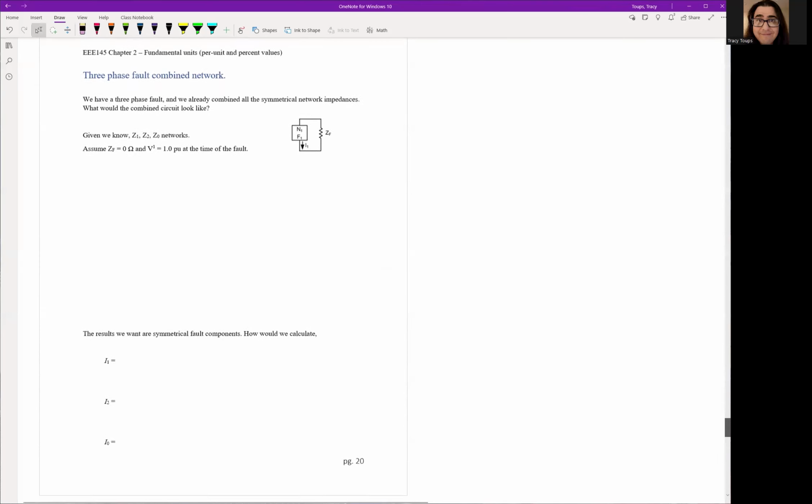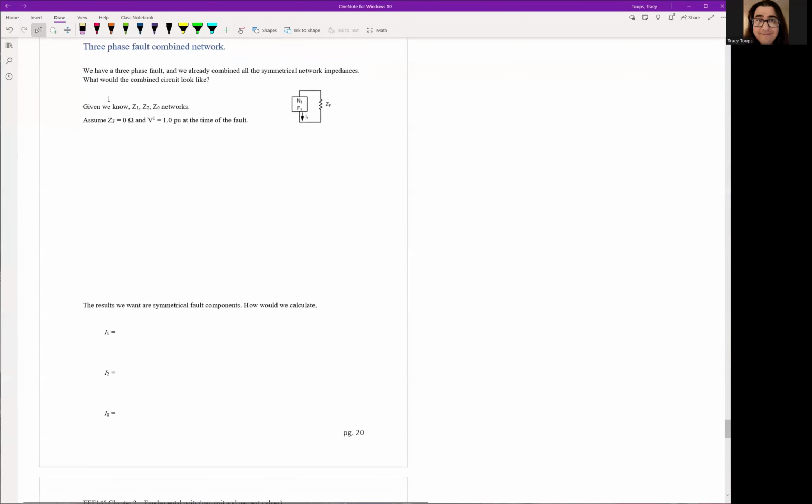The same fault point we've always been pointing at, the end of the transmission line. Let's figure out a three-line-to-ground fault. For a 3-phase fault, all we need is the positive sequence network, so we have the box with just the 1. So we would draw our circuit out. Now notice the way this particular diagram is shown, F1 is at the bottom and N1 is at the top. So we just have to flip our model around.